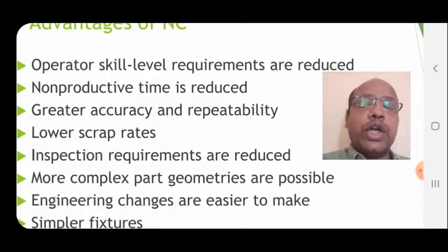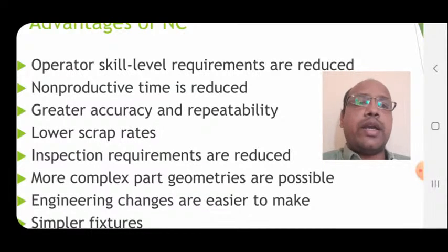You can go for a contouring NC system for getting different irregular geometries. In the last lecture, one student from our class, Raju Padde, asked whether we can go for irregular geometries. So yes, my answer is that we can go for irregular geometries by using circular interpolation commands.